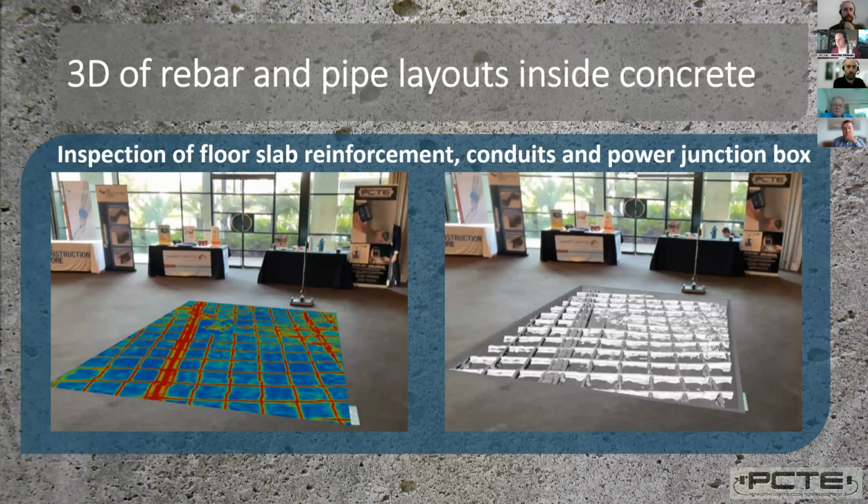So here's just another example. That's the GPR there. It's got a telescopic rod with the iPad mounted on top, and the probe's about 300 mil, but it's really good for scanning large areas. This again is about a 4x4 meter area we've scanned, and we found a number of conduits running in the floor, all headed to a junction box. You can see it in the top left corner of the model, in plan view looking down and also in 3D on the right-hand side. Again, it was about a 5-minute data collection. Each time you move the GPR, you do 6 lines at a time, so it doesn't take too long to do this type of 3D model. Yeah, and I think very powerful.